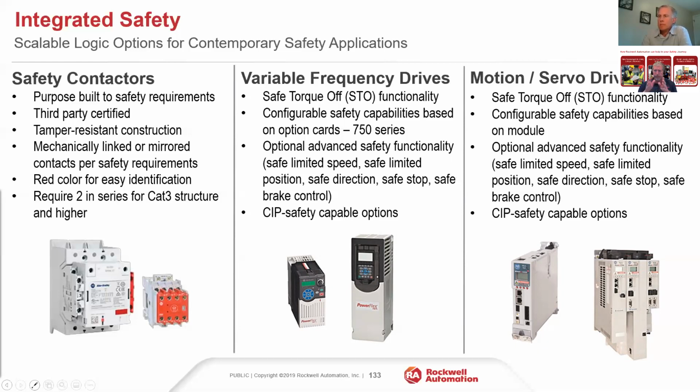And pretty much the variable frequency drive and the servo drives at this point from the Rockwell perspective have very similar functionality. In the 750 class, it's the S4 card. In the servo drives, it's the ERS4 is the latest, which is the CIP safety version that contains all the advanced functionality.